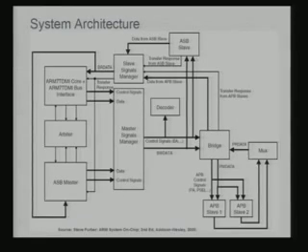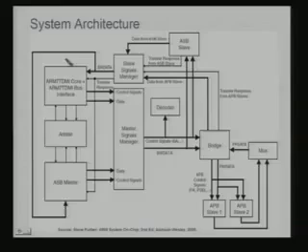In fact, the bus is a key issue for any kind of SoC design for embedded systems. I may have a very high speed processor, but if I do not have an efficient bus transaction protocol design, then I cannot really exploit the processor features. I may have multiple processors, but I will not be able to exploit their characteristics optimally unless I have designed an optimal bus connecting them, as well as the memory and peripherals.